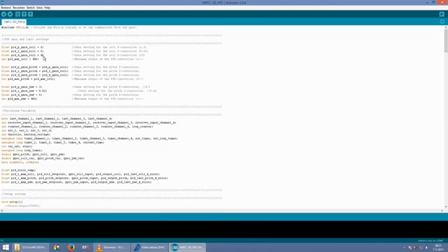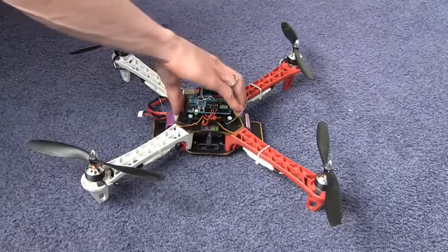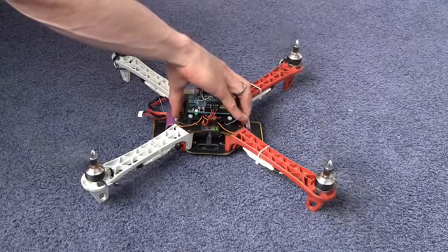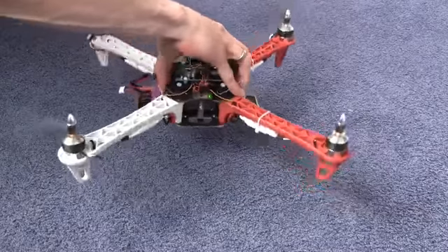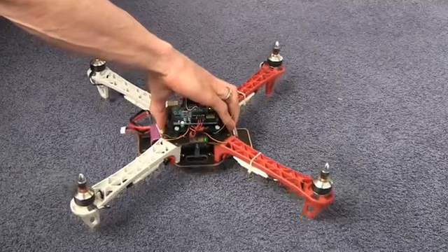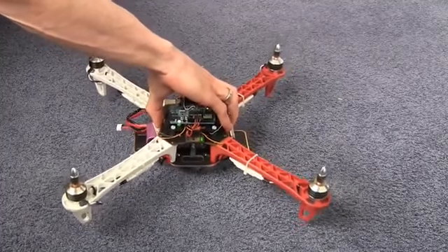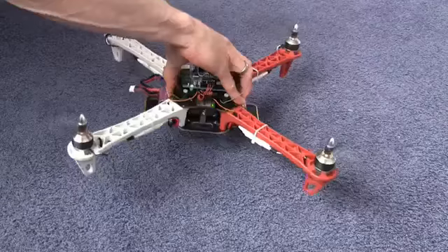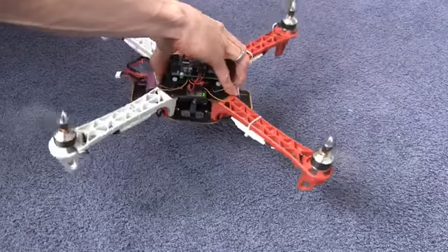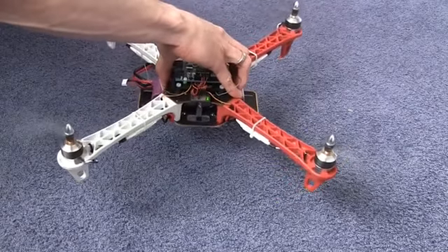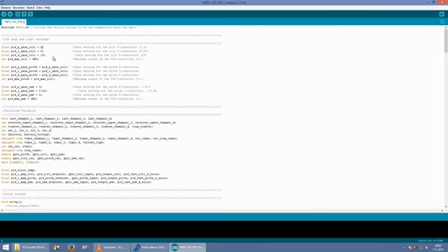Now in contrast to others, I always begin with the D controller. You set the multicopter on a carpet or grass and raise the throttle up to the point it almost starts to hover. Increase the D gain up to the point that it becomes restless. Lower the D gain until it runs smooth again. On my multicopter, this is 20. Then lower it again with 25%, giving me a final setting of 15.